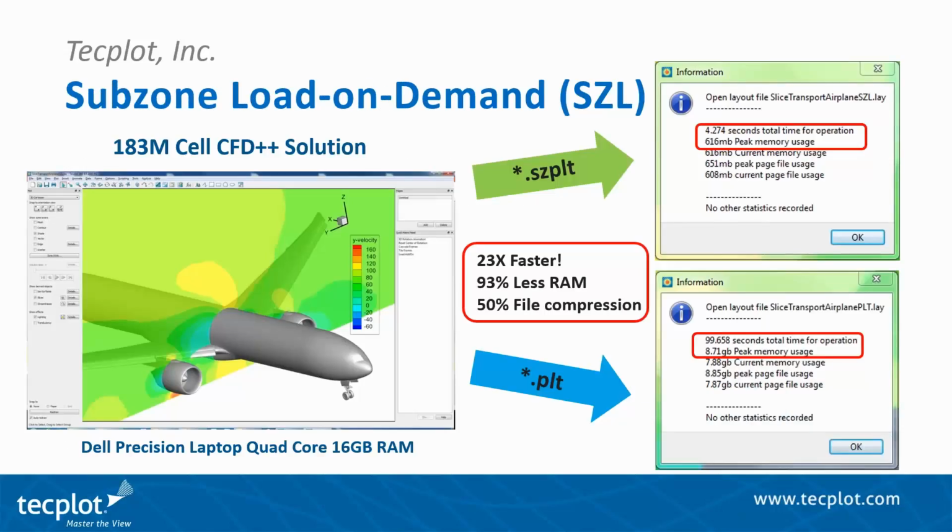The last bit of technology that I'll talk about is subzone load on demand, or SZL. This is an enabling technology for us that first manifested itself as a data file format. The idea here is to be able to load very large grids with a very small amount of memory, and also load them quite a lot faster. We found in recent years that the primary bottleneck in CFD post-processing has become the disk.